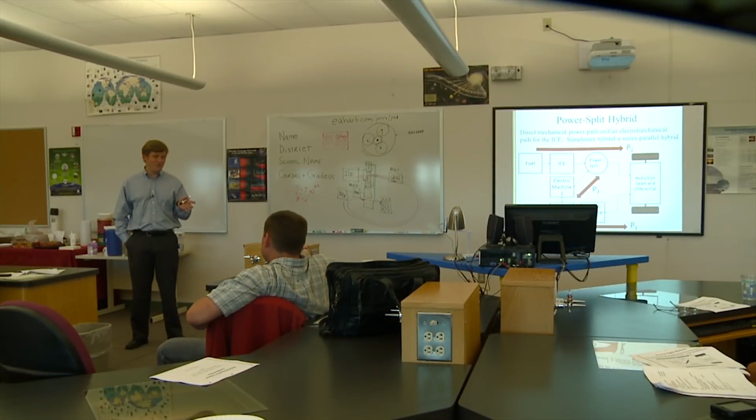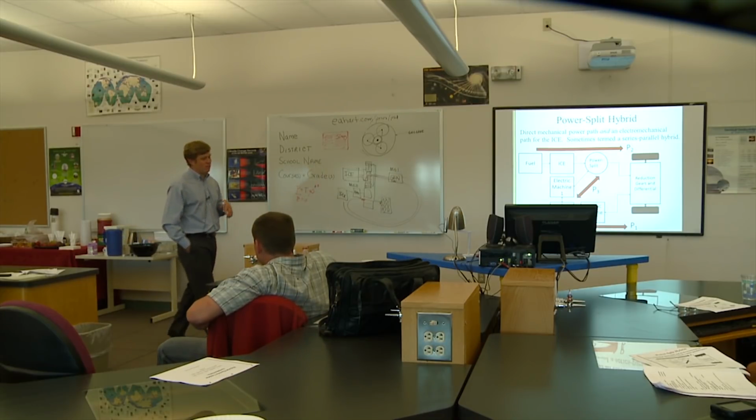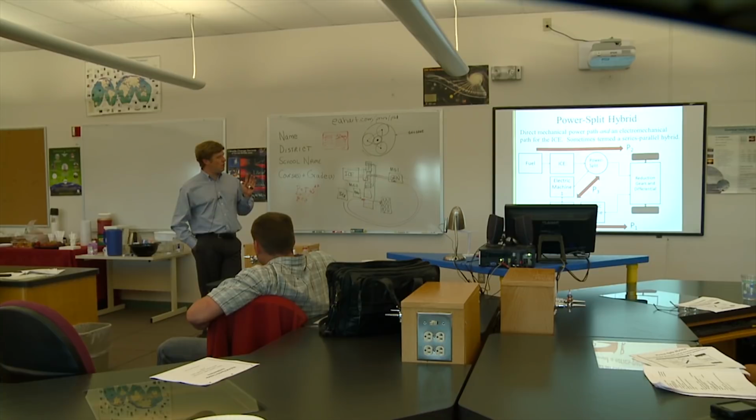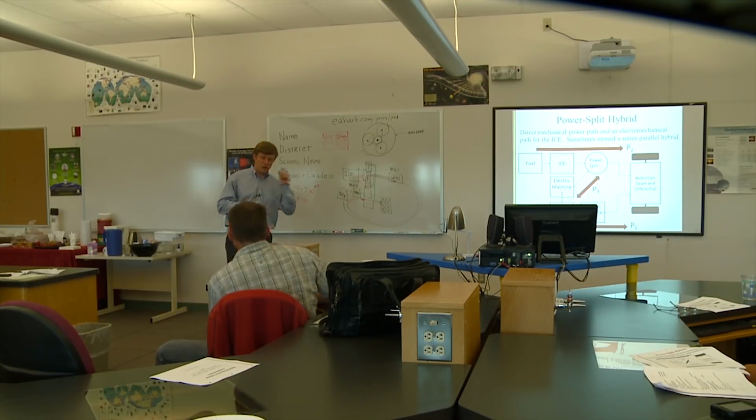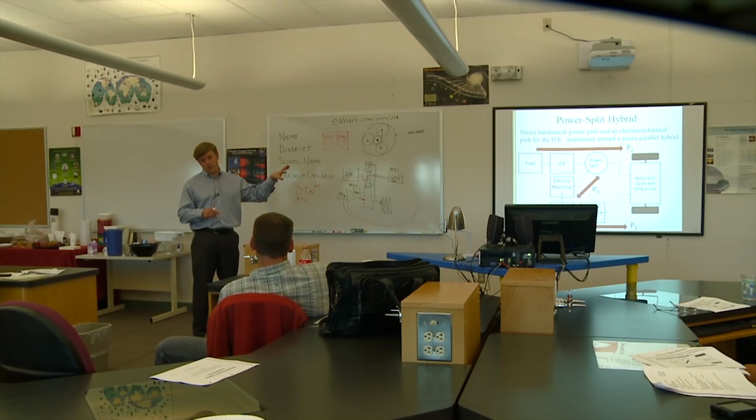So obviously Highlander is an SUV, almost a full-size SUV, and they wanted to sell it with four-wheel drive capabilities because people are willing to pay for that for whatever reason. My understanding, and I'm a little bit rusty, was that in the original implementation, they had this power split device with a front wheel, and Highlander's also front-wheel drive. So it's an all-wheel drive system. It's primarily front-wheel drive, and if it detects slip, then it'll power the rear wheels as well.